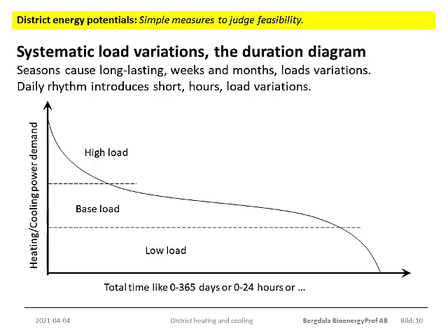Climate will cause seasonal variations, which are obviously the same to all customers. There will also be daily variations. These things hit all the customers the same way, and there is basically no random effect at all. So for these, there will be no reduction factor. The high load case for the system is simply the sum of the high loads for all customers.